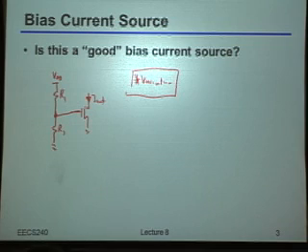Noise in the resistors. What do you mean by noise in the resistors? Okay, so you said the resistors vary with temperature. That is true, but this is one thing that maybe I actually did okay in this particular circuit, right? As long as I built these two resistors out of similar devices, and I did all the unit element matching tricks and things like that, at least I could claim that the resistive divide ratio is probably okay, because that only depends upon the ratio of those two resistors.